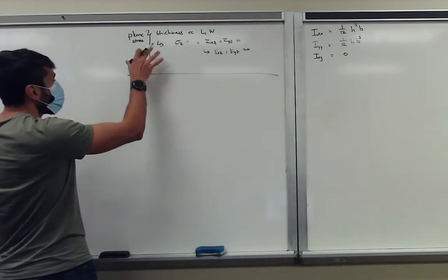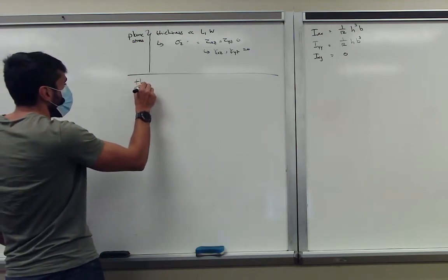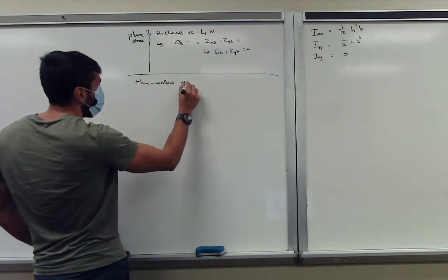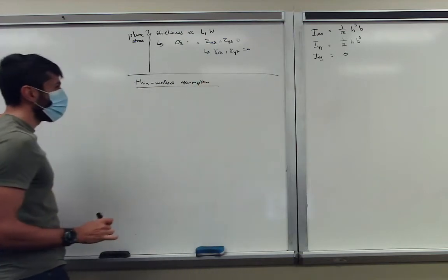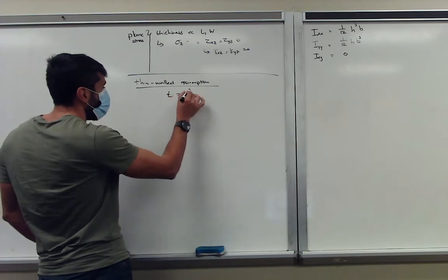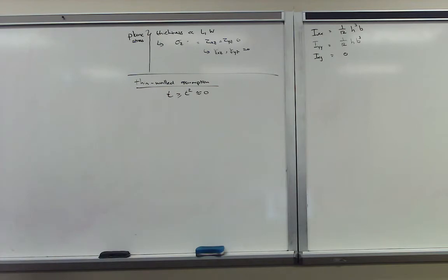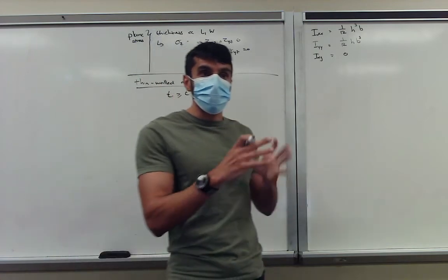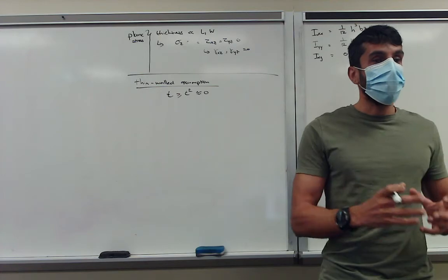So this was from a stress point of view. From a cross-sectional point of view, a similar assumption we make is also called the thin walled assumption. For the thin wall assumption, whenever we have t squared or greater, we assume it is equal to 0. So whenever we see a t squared or above in our equations, we say that the contribution of that part is equal to 0.